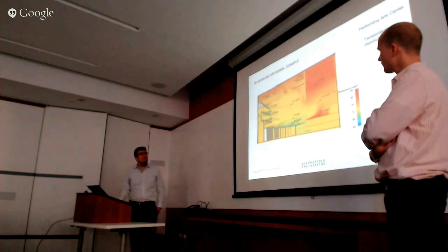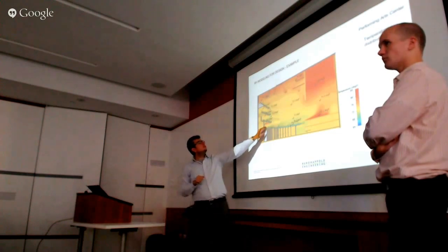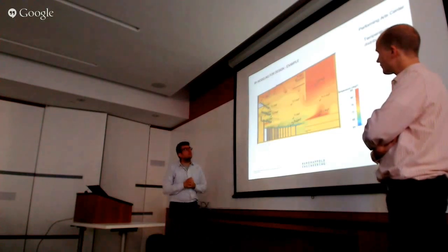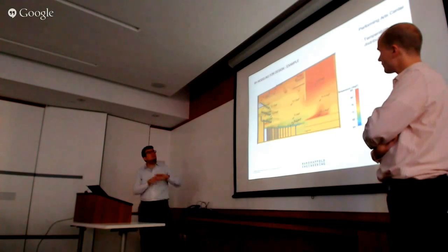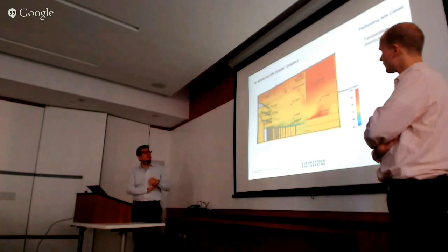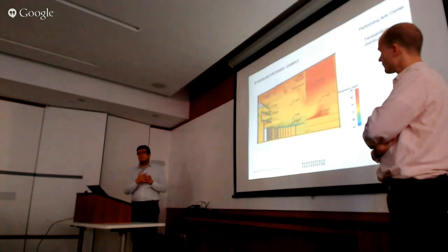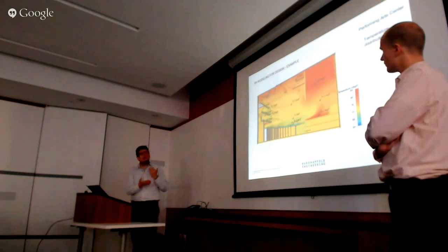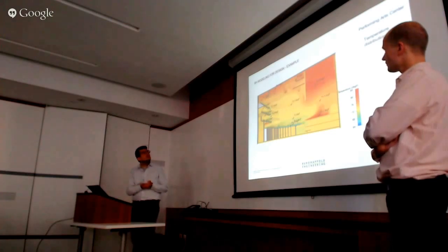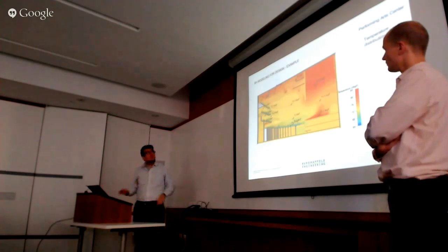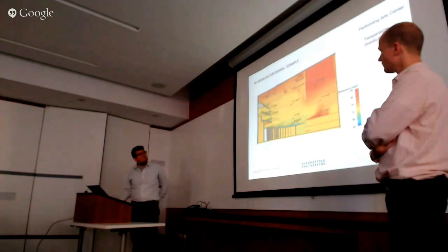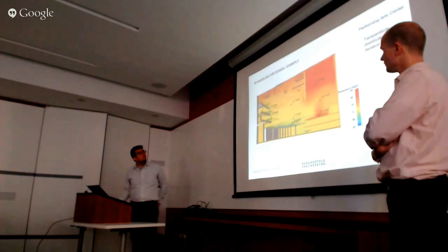Now this was the first iteration without those return grills at the first level. So we would see considerable heat buildup, reaching 80 degrees at the hottest spot anywhere where the seats are. That was not only undesirable, but would also give a very bad impression as you step in. If you're getting hot air, you're also probably getting stuffy air, so carbon dioxide and everything else would build up there. So that's what it told us. We saw that, made changes. This is before that change.